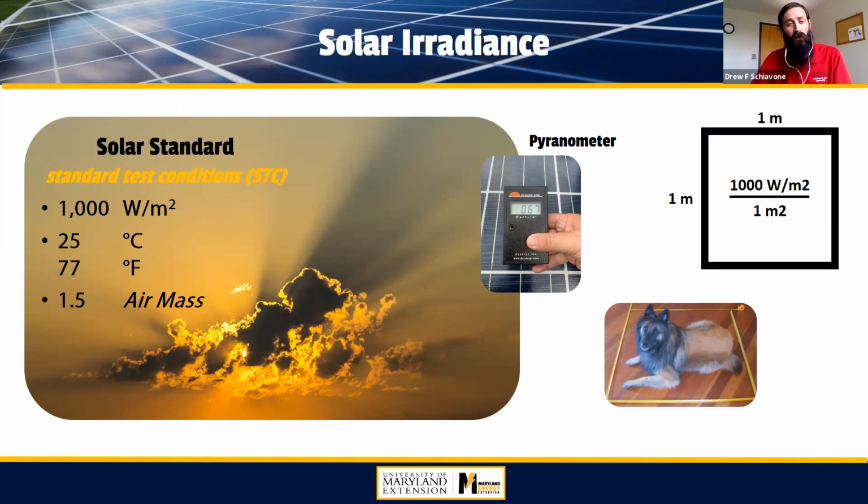The higher temperatures impact your voltage, and as a result, you get lower efficiency at those higher temperatures. And another expression, air mass, which includes clear skies and humidity and other factors. We don't necessarily have time to get into all that detail today. But this is what most panels are tested on under these conditions.